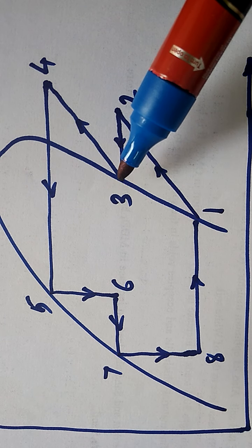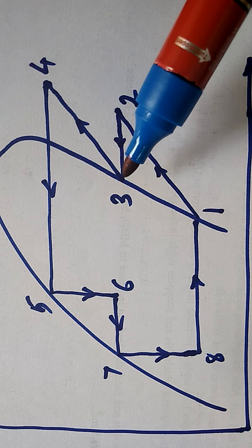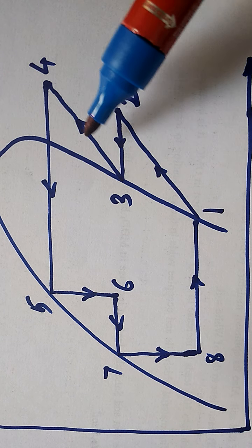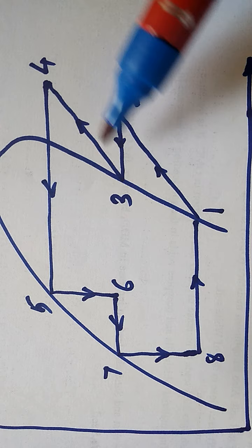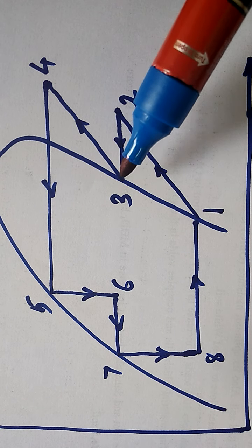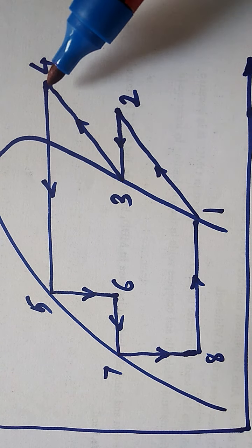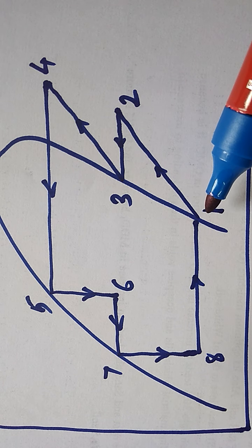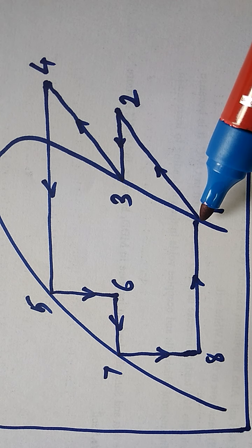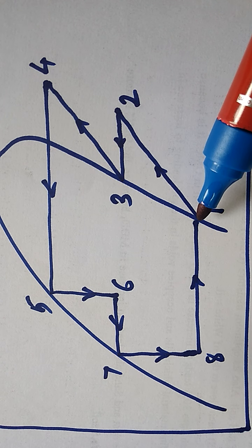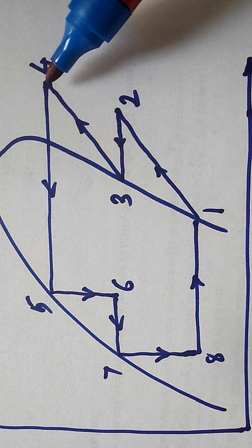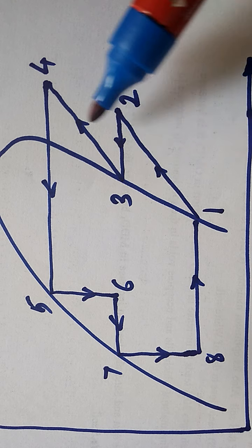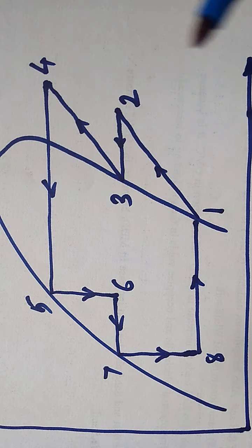That dry saturated vapor is then compressed in the HP compressor, that is the high pressure compressor, from state 3 to state 4. So in short, rather than compressing the vapor refrigerant from state 1 to state 4 in a single stage, it is compressed in a double stage. Then you may ask, what is the advantage?